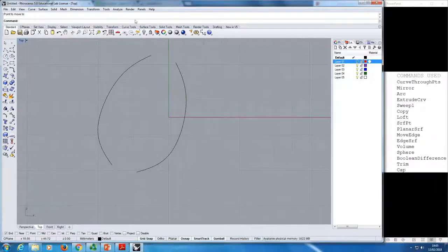Next, we'll create an arc. These are all of the arcs you can create. You have different ways of doing it. Otherwise, in the command line, you can just type arc. Here, as I said earlier, you have options on how to do things. If we select start point, you have the S that is underlined. Either you can click on it, or if you type S, then it will do it for you.